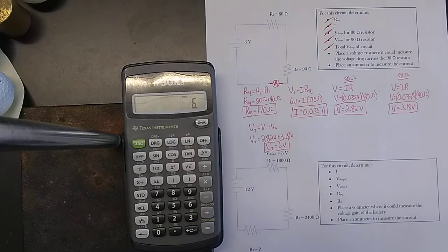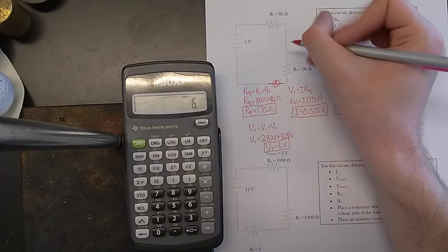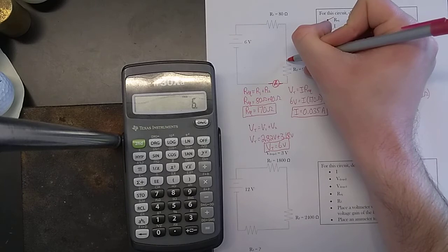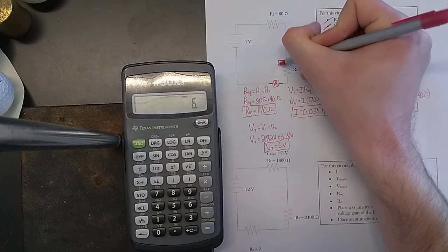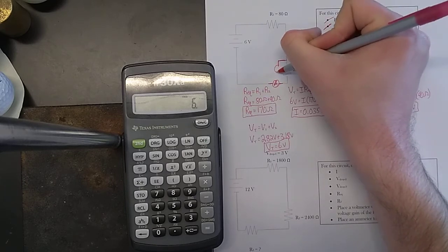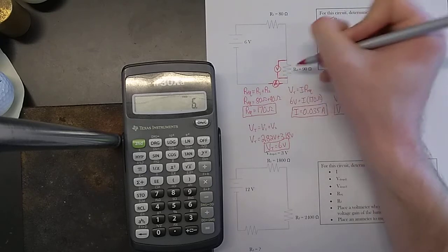That is an ammeter. Now the voltmeter has to be drawn very specifically, and this is the one that people mess up. Remember, in the simulation, you didn't just wire the voltmeter into the circuit. You had the two little probes and you put them across or around the resistor. That might look something like this. See how these are the little probe arms here? Here's the voltmeter, here's the thing that's actually reading it, and they go across the resistor.